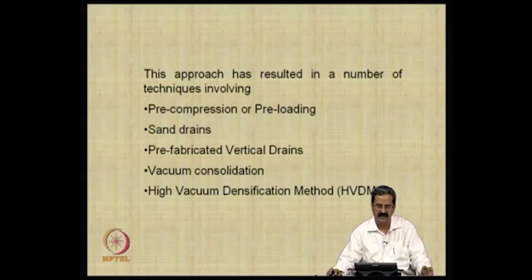In this technique, we apply a higher stress than the stress that is likely to come on the soil, so that the settlements are preempted. We accelerate the process of settlements by using preload, and once you construct the structure, you will not have much settlement. That is what we call pre-compression or preloading.